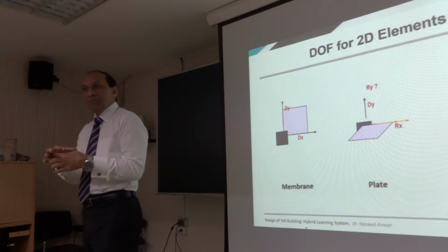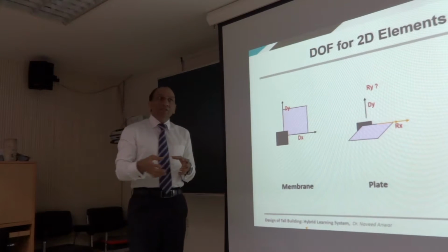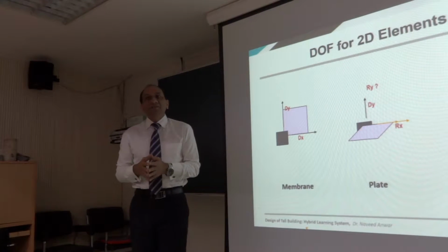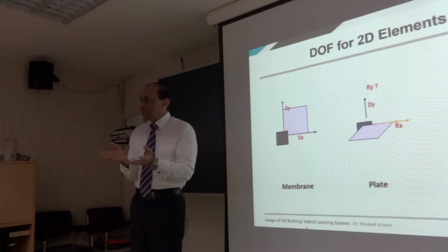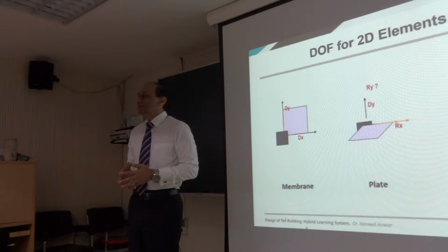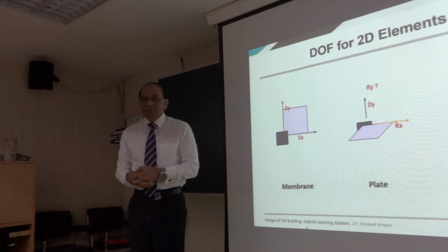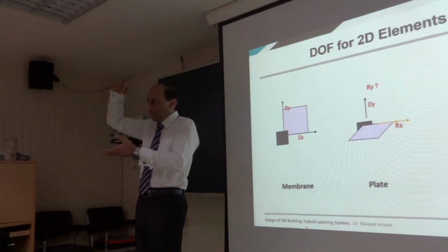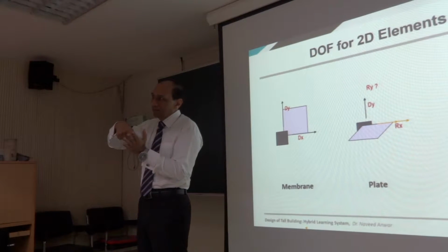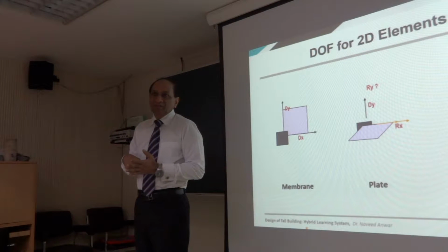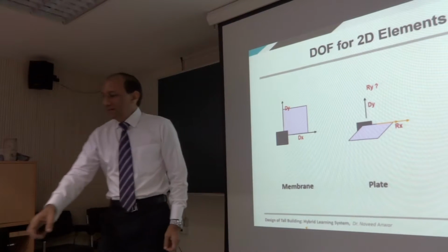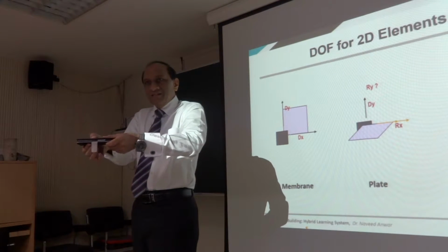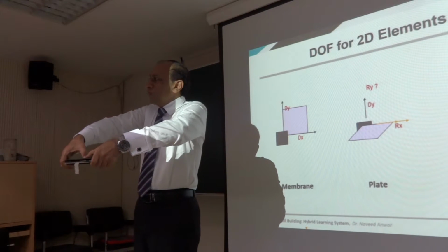So, circular pipes, shear walls, beams, steel sections, open sections, everything like this, which can be divided into surfaces, can be modeled as membranes. Plates, wherever you need to transfer loads which are applied perpendicular to the plane, then you need a plate. A plate needs bending stiffness. So now I need this one. I need something that has thickness and stiffness. So if I apply load here, it won't bend.